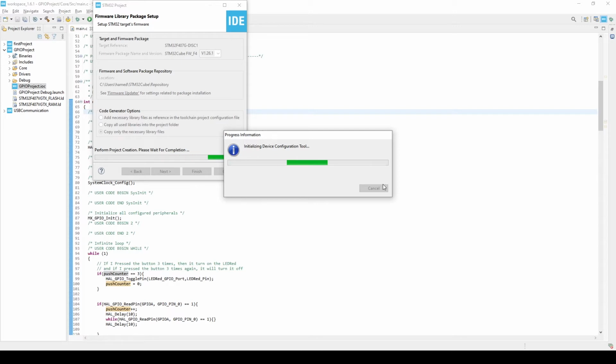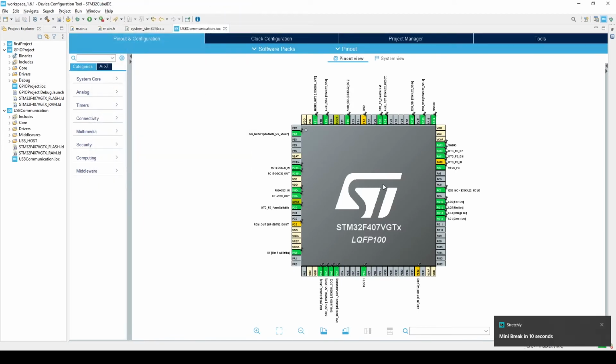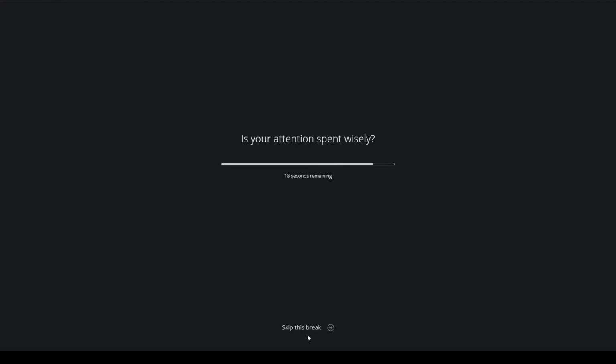So clock basically is the main thing that controls how fast your microcontroller is running the instructions that are saved in the flash. I know it's a bit hard to understand because you probably need to pass the microprocessor course to fully understand that, but in simple terms, clock is controlling how fast your microcontroller is running some instructions. Okay, so since we need the clock to be at a specific value for this project,